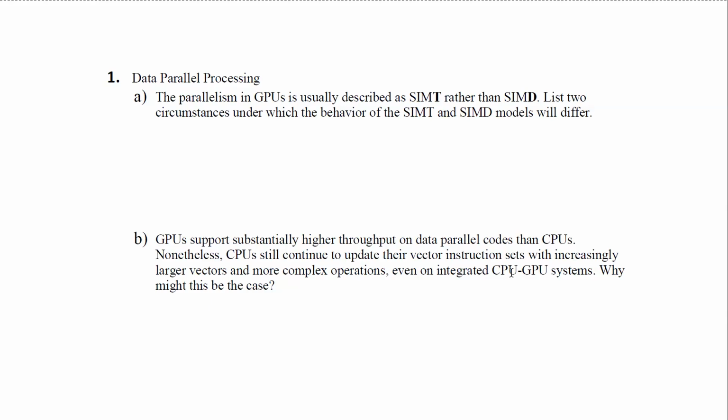Getting one instruction's worth of SIMT execution to occur on the GPU takes a lot of effort. There's a lot of time to get the data, send it to the GPU across an I/O bus, get the kernels communicated, go through the schedulers. So the GPU has enormous throughput, but there's enormous latency to get that first piece of data out.